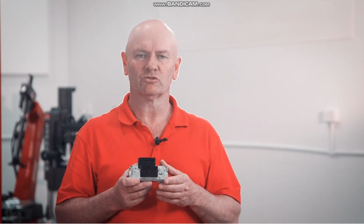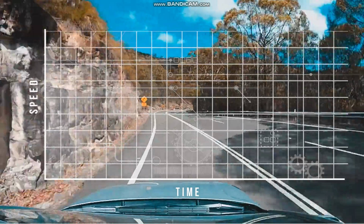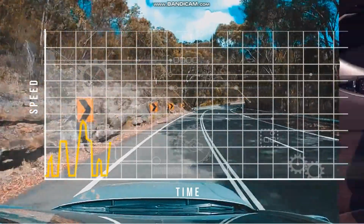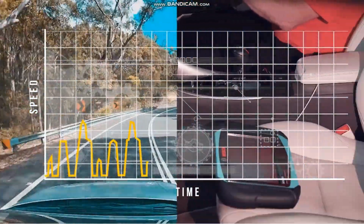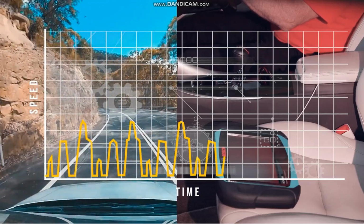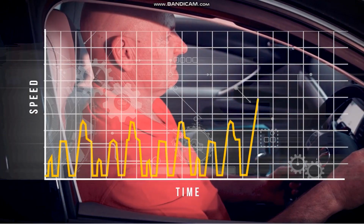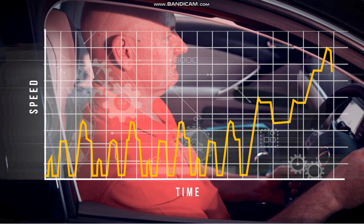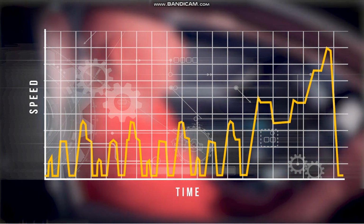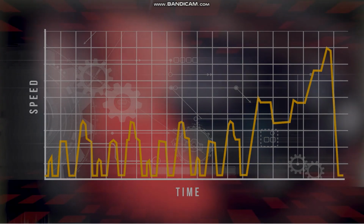A combination of the system monitors may be run concurrently or in succession as part of an overall process referred to as a vehicle drive cycle. A drive cycle is often specified in OEM service information and can often be quite extensive. Until the complete cycle or monitor has run, the success of the repair cannot be completely verified. In practicality, however, this is often very difficult to achieve, given the very specific requirements of these drive cycles.